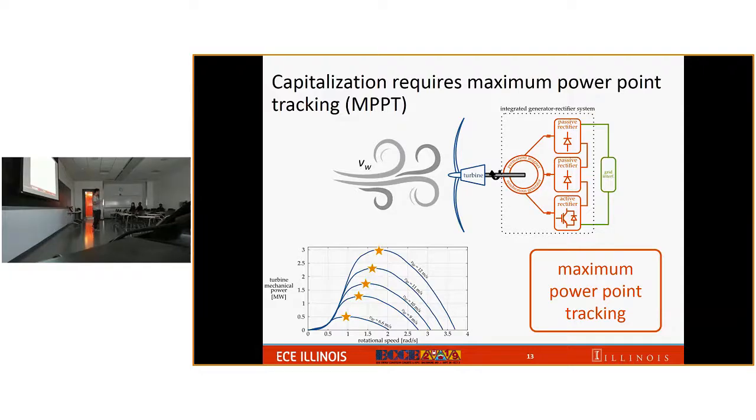So when we look into this architecture, it seems to be difficult to control the power flow. The reason is the appearance of the passive rectifier, comprising diodes, in the system, and we all know that with a passive rectifier you cannot actively control the power.